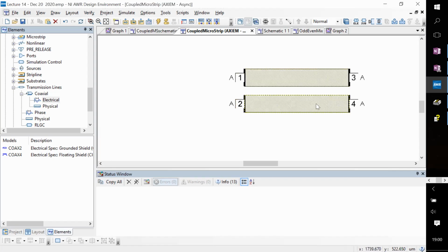And then that will propagate through this system, experience any reflections or not on the other side, and give rise to either a reflected wave, which will again then come here and then, depending on the port impedances, transform. So that has to be set up correctly if you want this 4-port device to have a particular kind of response which you're trying to design. So one device, which is commonly designed using this technique, is called a directional coupler.